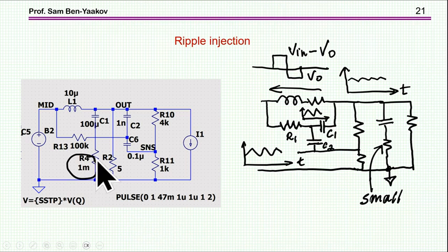As I've said at the beginning, the whole idea is that you need ripple. To get the ripple in the conventional way, you need a resistance here, and if the resistance of the capacitor is too small, you might add a resistor. This is not a good idea. You don't want that high a ripple at the output. You like it to be as smooth as possible, okay?